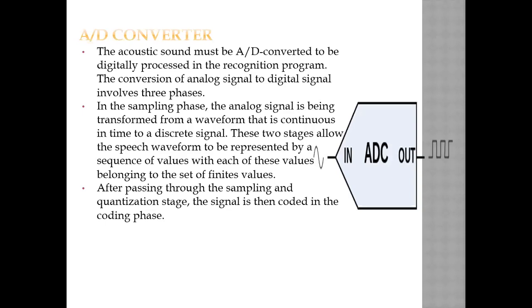So therefore, whatever digital output comes out may not match the input point. A critical analysis has to be made of how much signal has to be given and the processing time, so that the signal will not be lost during the conversion time. The A to D converter time is very, very important, otherwise things will not be perfect.